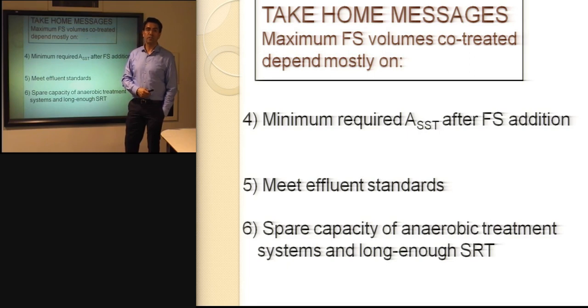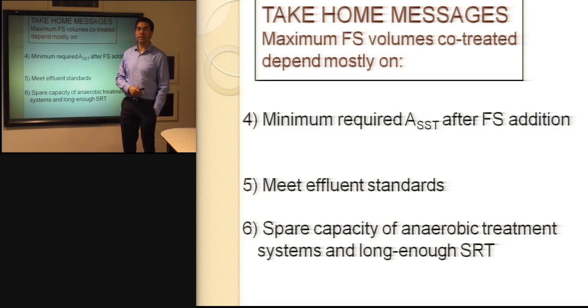So to co-treat the fecal sludge in an existing plant may not be the best choice. On the other hand, if the plant is going to be designed for the co-treatment of fecal sludge, very likely the system needs to be very large and robust, more robust than usual to treat wastewater, because of the particular nature of the fecal sludge.